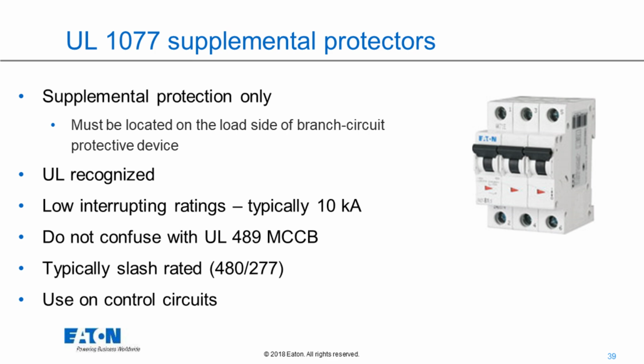A specific application could be a luminaire that has been listed by UL with a supplemental protector, fuse, or a protector like this device here. Again, it's for specific applications, and it has to have some branch circuit protection upstream. Used on control circuits a lot.